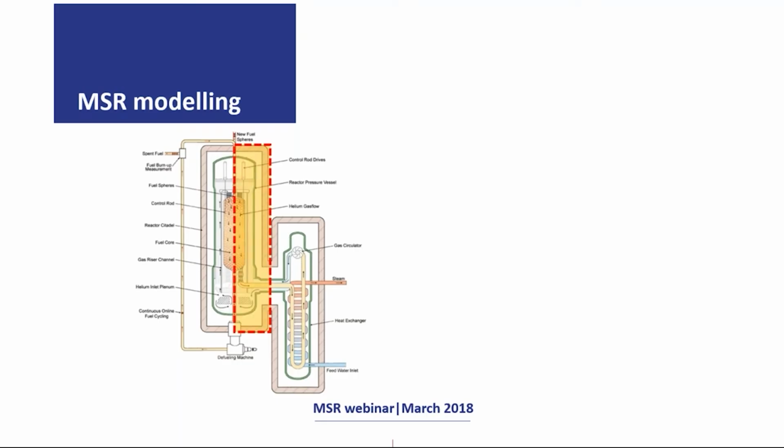In Flownex, we have an axisymmetric approach. That means that this block here that I've drawn, just get to that quickly again. So this block here will be what we model in Flownex, and then that will be revolved 360 degrees in order to form an axisymmetric reactor. So in our approach, it's important to remember that it's been set up in this way. So we'll just be building a reactor, half of it in one plane, and then that plane will be revolved 360 degrees. Okay. It will look something like this.